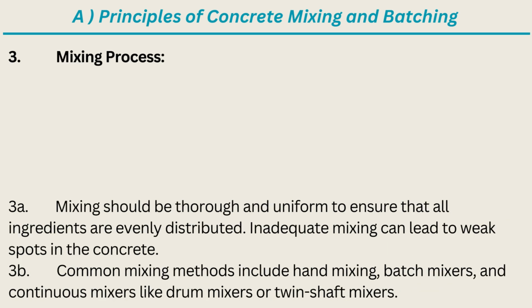3. Mixing process. 3a. Mixing should be thorough and uniform to ensure that all ingredients are evenly distributed. Inadequate mixing can lead to weak spots in the concrete. 3b. Common mixing methods include hand mixing, batch mixers, and continuous mixers like drum mixers or twin-shaft mixers.